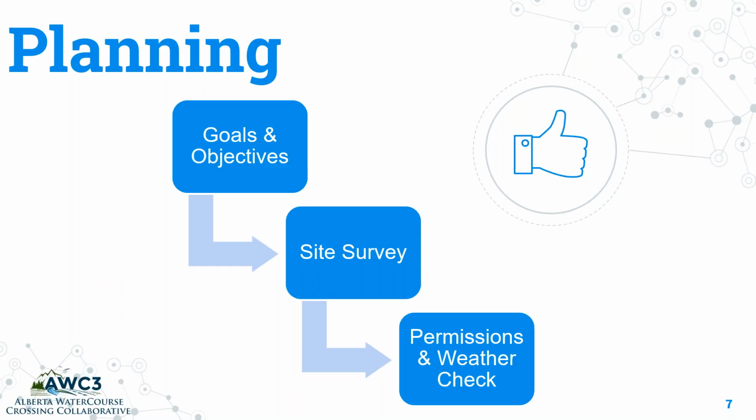So permissions, there's a lot of suspicion around drones, and people typically don't like it when you're flying a drone without permission. And so you need to ensure that you have permissions from all the site managers and from the company that you might be working for, especially if it's not your own company, before you go on site. I always have my permissions printed out with me so that if anybody does approach me on site to ask me why am I flying into this area, I can give them the paperwork and say such and such person gave me the authorization to fly this area.